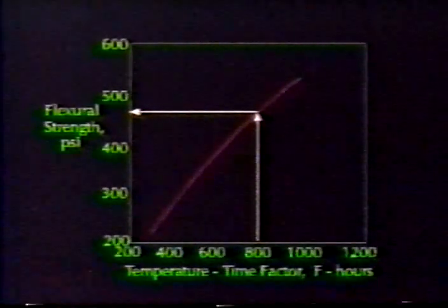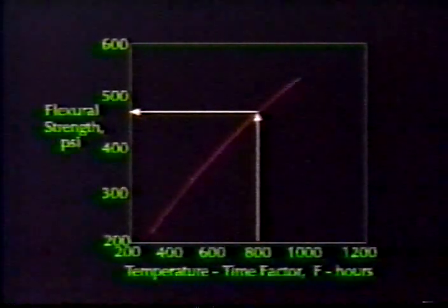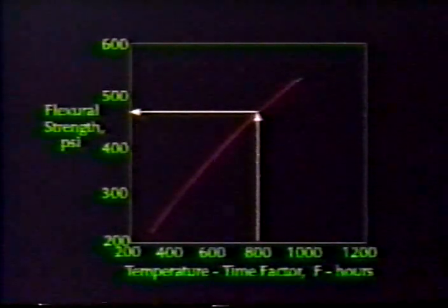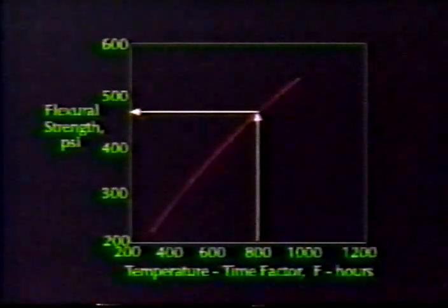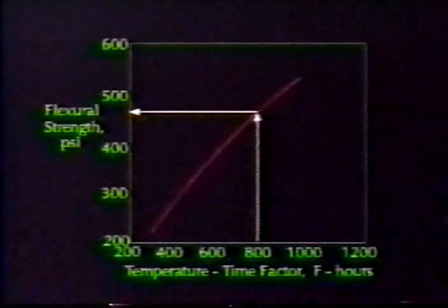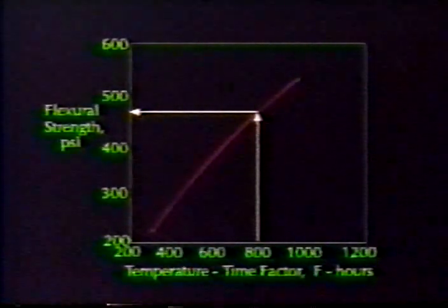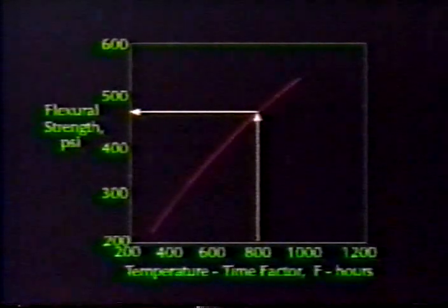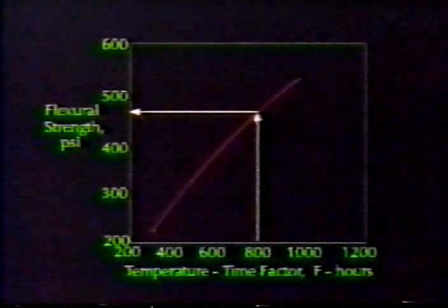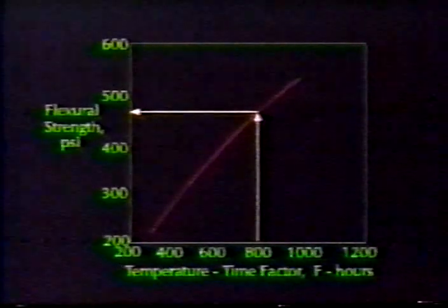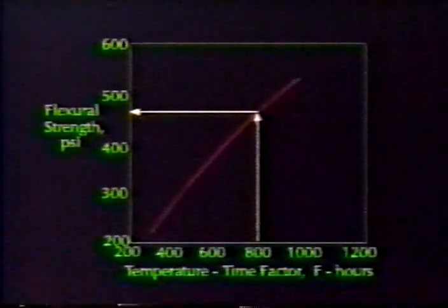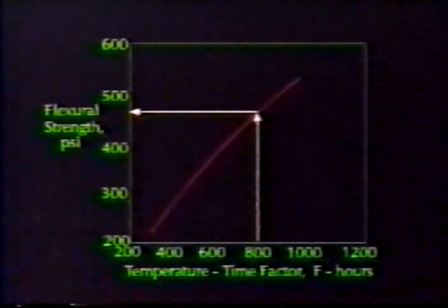If flexural strength development is to be monitored from 200 to 500 psi, specimens should be tested at several ages to develop a relationship which is applicable to the strength range. At least 5 to 10 test periods are typically used to establish strength maturity relationships. The maturity for each strength test is computed, and the relationships predicting strength from maturity are established.